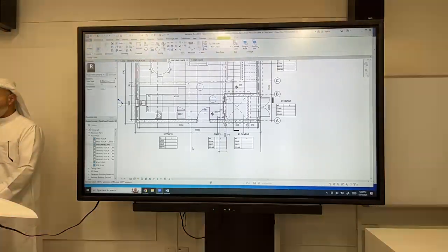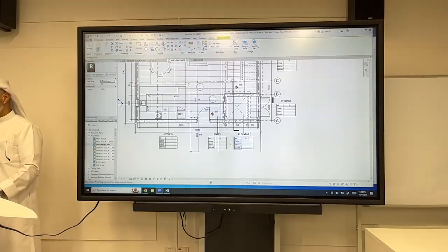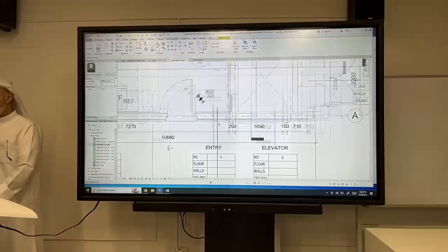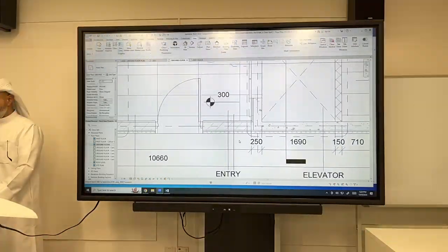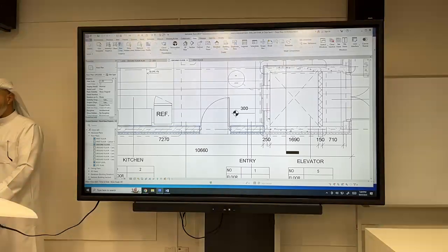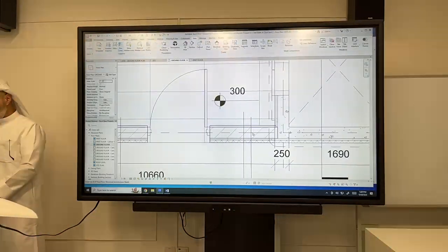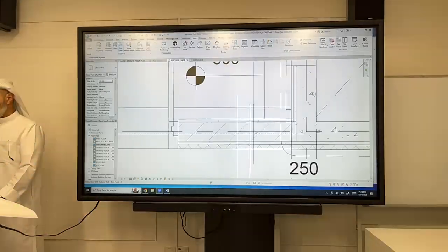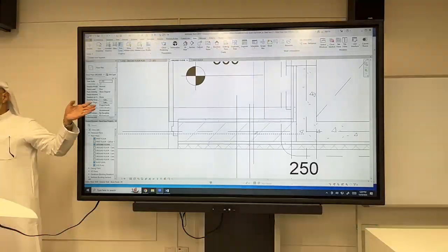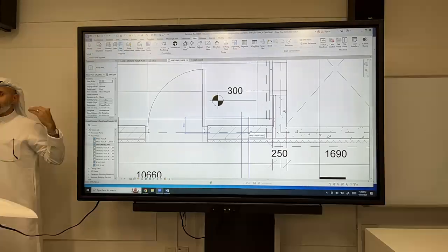Now I have two guidelines that I know are even numbers from the edge of the wall. Okay? Once I have that, make sure you're not confusing it with other lines, because you're going to see other crossing lines. Same as this. SL to split. Now what I want to cut is the wall. But if I come over the line that I drew, it will not select the wall.